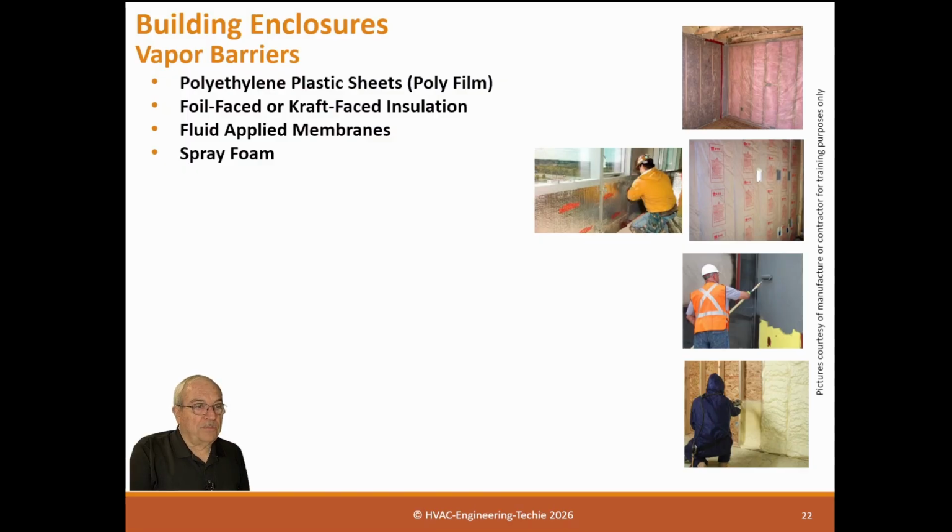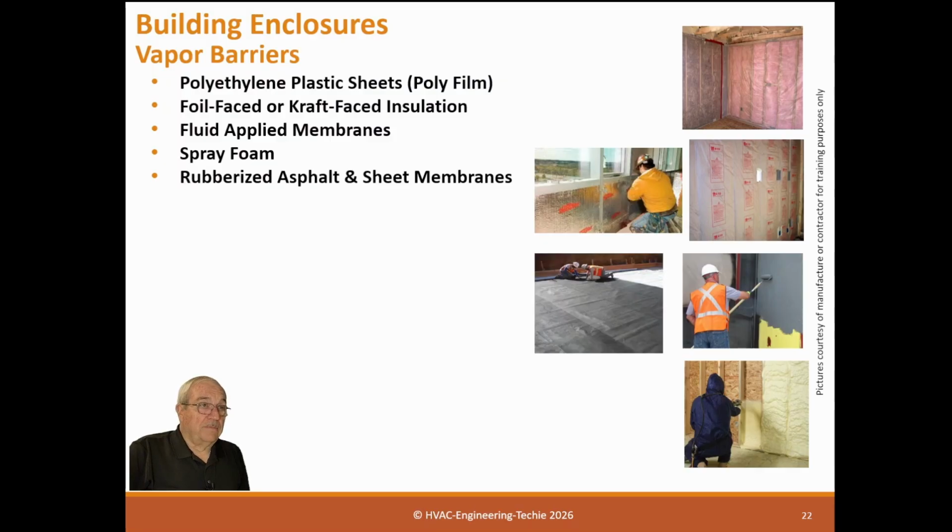You have to deal with this problem: it does outgas certain gases that are not desirable. So once you put it in a building, you have to air that building out for several weeks. Don't cover it right away, because then you may have an air quality problem inside the structure, especially if it's a residence. They recommend at least 2 weeks of uncovered foam to outgas prior to covering this wall with sheetrock.